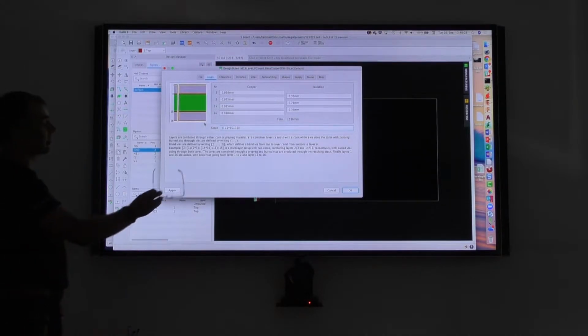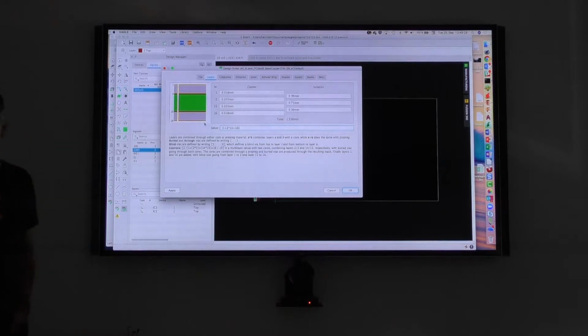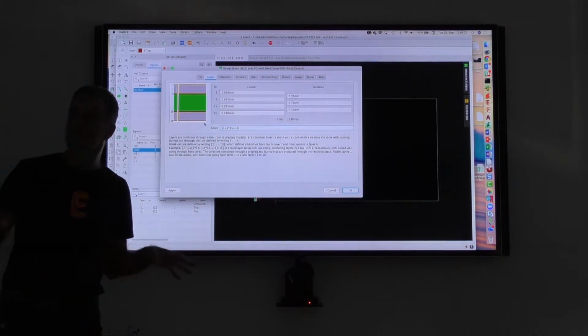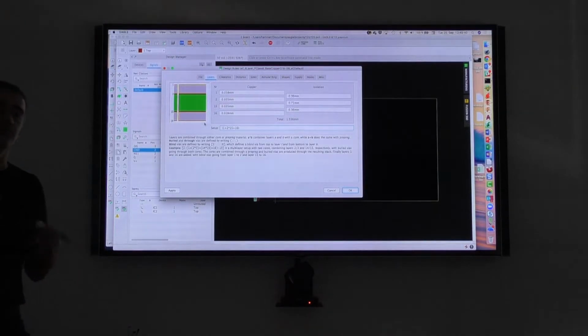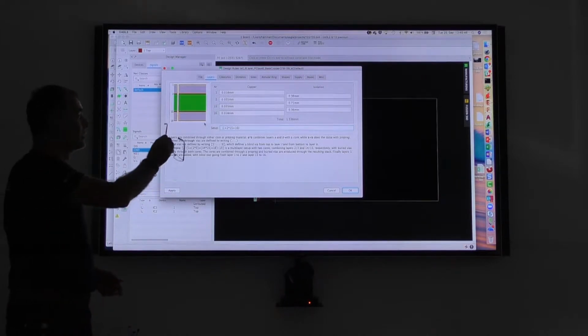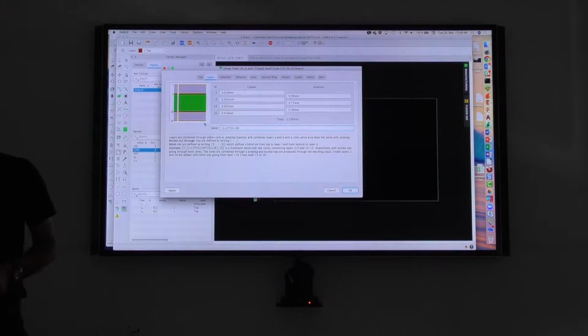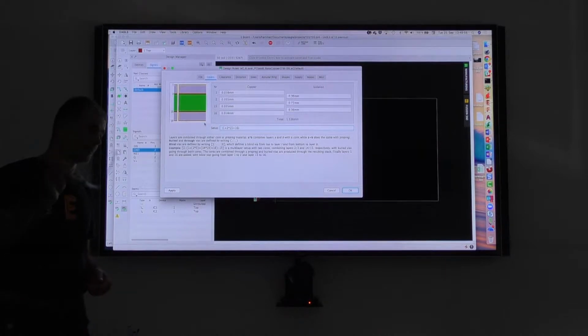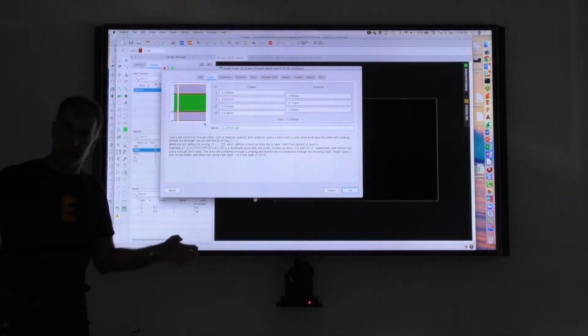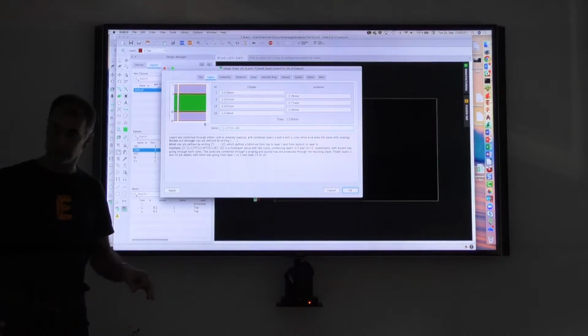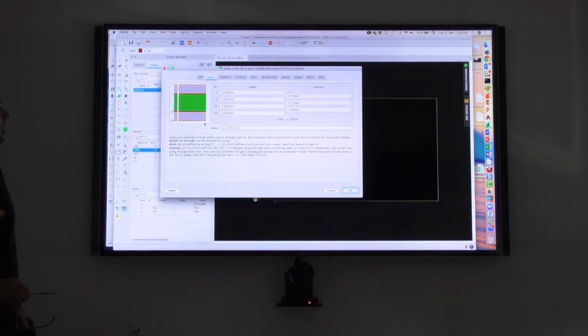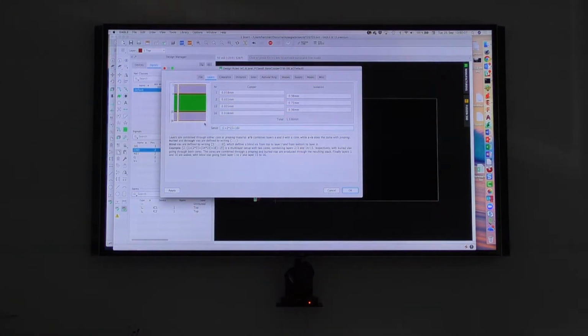I have layers. We have a maximum of 16 layers in Eagle. But in most cases, you build a symmetric board. So 1 is always top and 16 is always bottom. If you have the freeware, you have to use layer 1 and 16. If you use standard, you should use 1 and 2 and 15 and 16. And if you have more layers, then you say I have 1, 2, 3, 4, and I have 13, 14, 15, 16. So I go 1 down and from down 1 up, for the number of layers. And yes, basically it's not very critical.